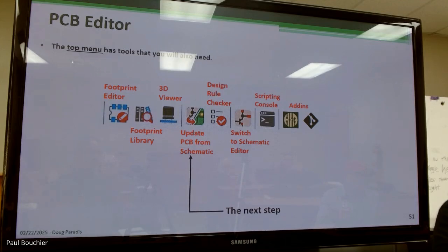And so when you create your board, you can actually make a 3D rendering of the board when you see it. It sounds great, and I can see where it'd be useful, but the problem is we created some of our own footprints. We're probably not going to go through the trouble of creating a 3D model for them. So it's of mixed use.